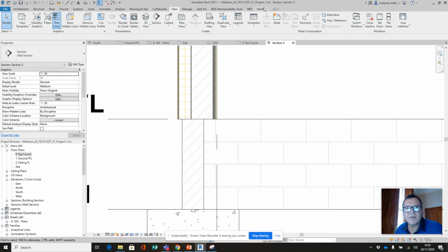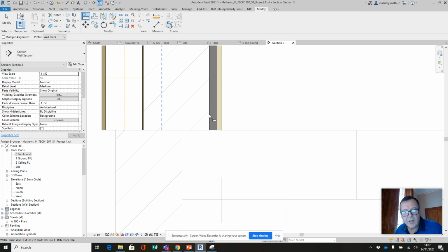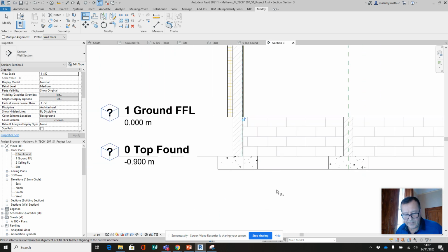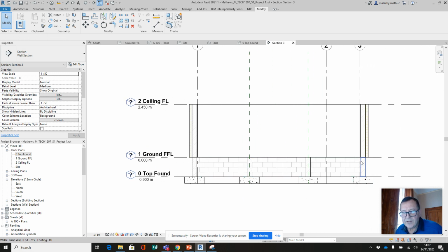the quickest way to fix that is to go into modify and use this align command. Now, so I want to align to the outside of the wall. So I'm hitting the tab button to select that. I'm saying to this, align this, and look, you're back in business there. Escape, escape. Okay. So that's correct there. Right, that is where we are.